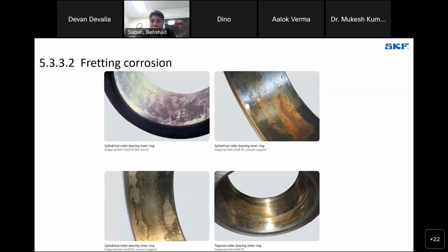Mind you, as part of the installation process, there is a recommendation to wipe off, with a lint-free rag, as much as possible, the bearing without introducing contamination into it. But one way to deal with that is to just flush it. You flush it out. Certainly, spray some solvent and clean it as best you can if there's any concerns. But worst case, because certainly larger bearings have a lot more corrosion inhibitor to the point where it's dripping off the bearing, in that case, it might be necessary to confirm compatibility.